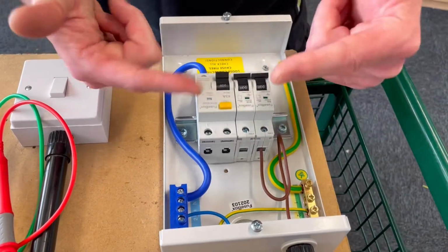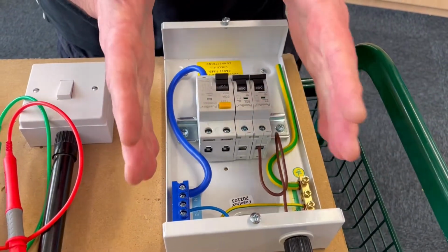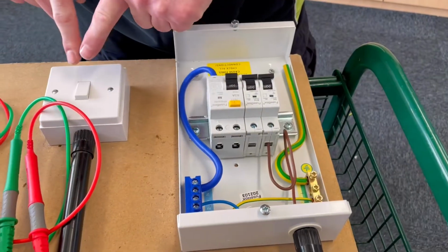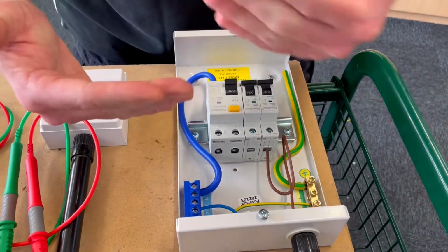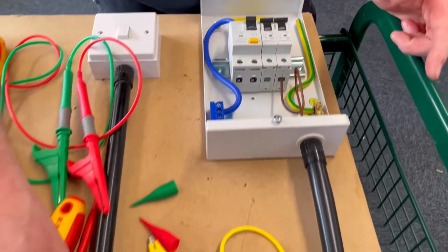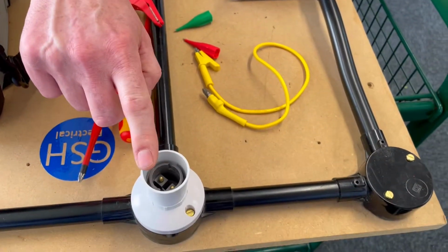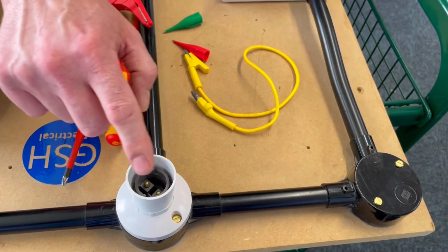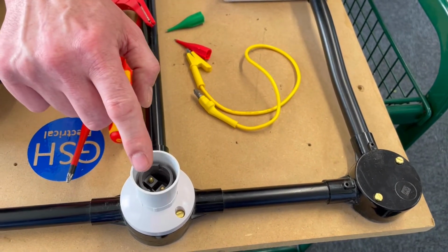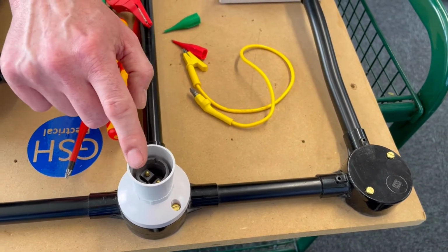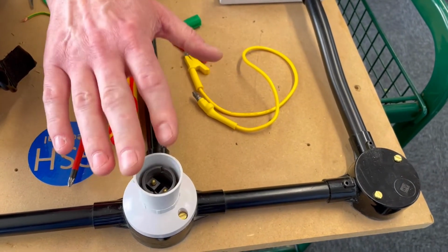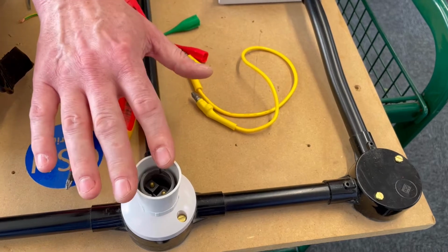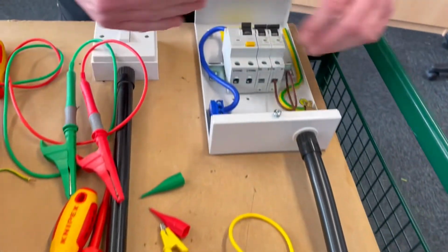But let's think about the things that we must make sure are in place before carrying out this test. We said that the switches, and there's only one in circuit, need to be left on. The lighting point is back and covers are on, but the lamp itself has been removed. If we had the lamp in here, it would be connected across the 2 pins, and that would be switching line and neutral, and would cause you an issue with your reading. So all loads need to be removed, because loads are naturally connected across line and neutral. All switches are on, all covers are on.